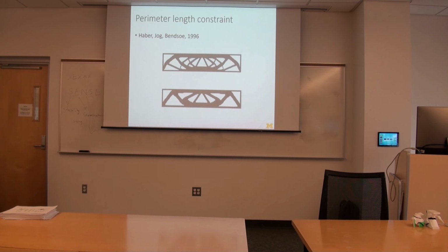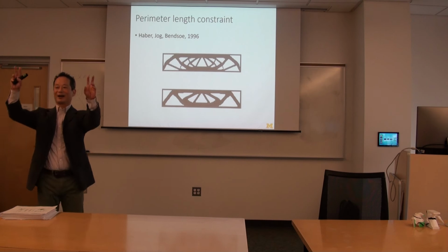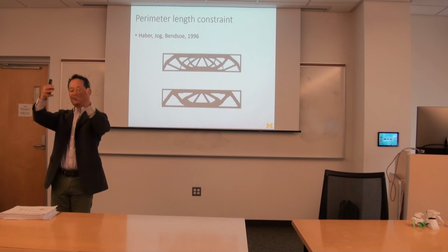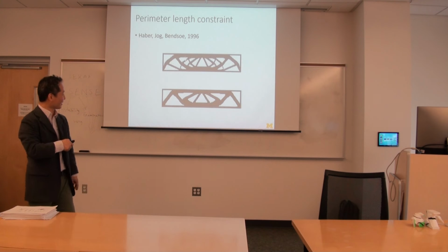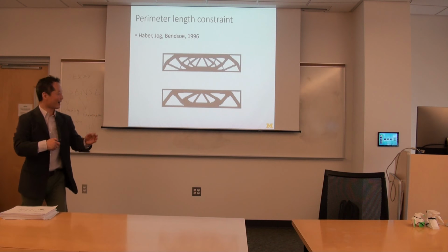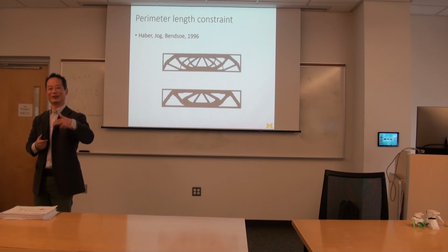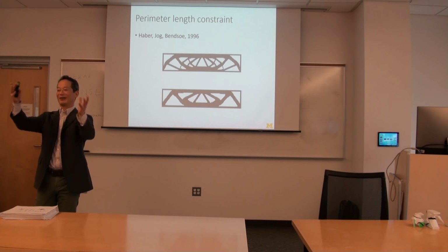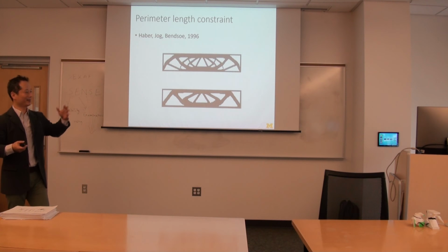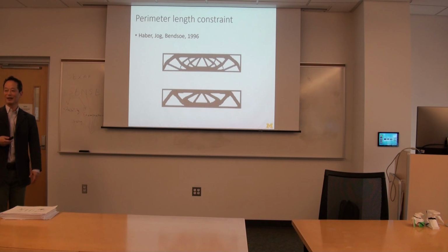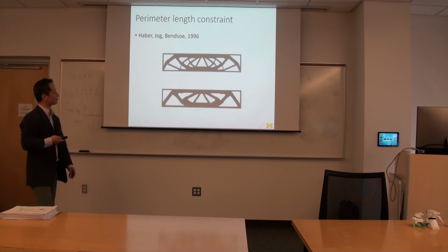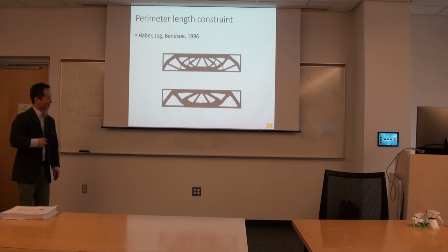Some people, in the topology optimization world, actually came up with a generalized concept of a perimeter length of, again, a point cloud. Okay, it's always a cloud which gives us a headache. If it's really a black and white result like this, which only appears at the end, measuring a perimeter is not a problem. But doing so while the convergence is not done, when everything is looking like a cloud, is a challenge. But we didn't invent it, somebody did it. So it's a generalized concept of a perimeter based on density, and we simply applied it. So this was a long perimeter versus the short perimeter result.